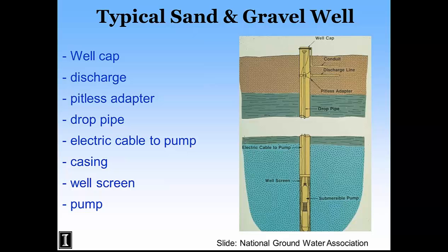So in this case, it shows a submersible pump. When your water level is more than 25 to 30 feet below ground surface, you need a submersible pump in your well, or well, there's a couple other types. But if you have very shallow groundwater, if your water level maybe is only 5 to 10 feet below land surface, then you're able to use a pump, maybe even in your basement, and you may have that situation because a pump can lift about 25 feet of water, and so it depends on your situation what type of pump you might have.